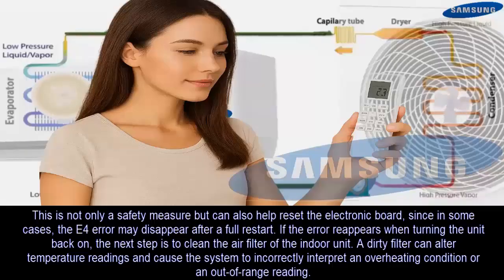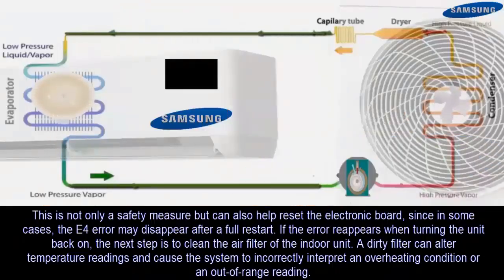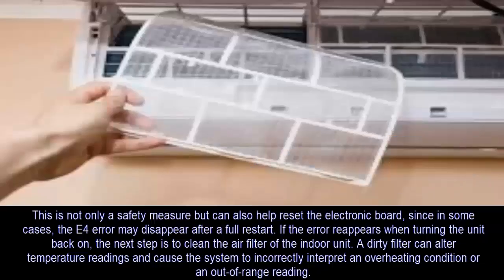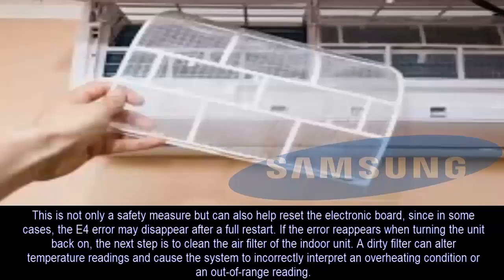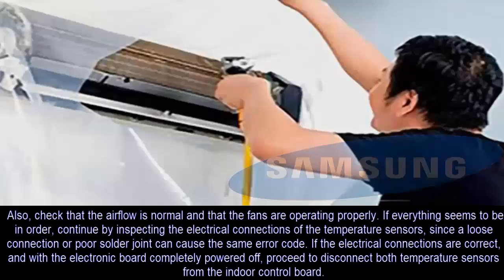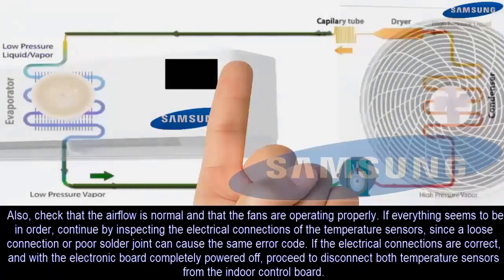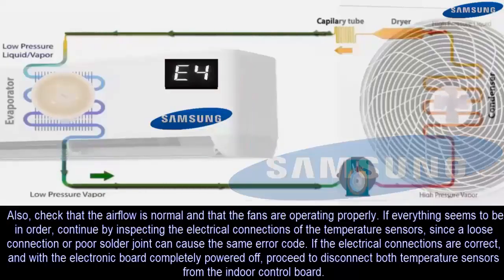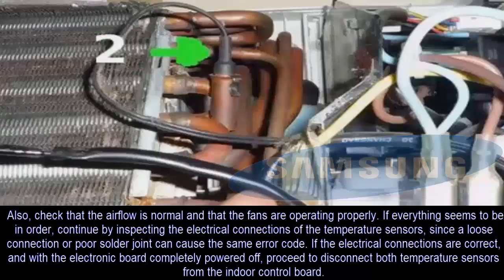If the error reappears when the unit is turned back on, the next step is to clean the air filter of the indoor unit. A dirty filter can alter temperature readings and cause the system to falsely interpret an overheating condition or an out-of-range reading. Also check that airflow is normal and that the fans are working properly. If everything seems in order, continue by checking the electrical connections of the temperature sensors, since a loose connection or poor solder joint can trigger the same error code.